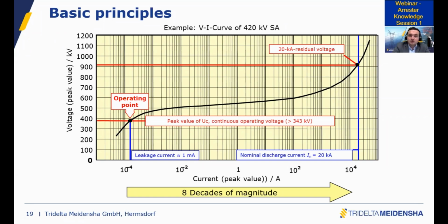What do you want? In your case, if you have a 550 kV system and you want 420 kV rated, it means that you want to withstand a specific TOV value. Typically phase to ground, the surge arrestor should be able to withstand 420 kV phase to ground with prior duty for 10 seconds.